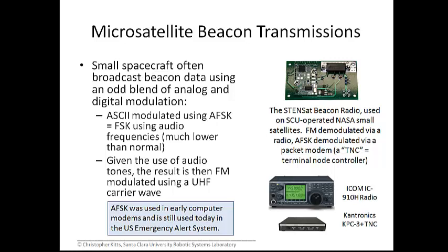So we're not doing direct frequency shift keying of our primary carrier wave. That's not what we're doing. What we're doing is we're frequency shift keying a much lower wave, and then we've created this new wave at a lower frequency, and we use that as the equivalent baseband to do standard FM modulation of the UHF wave. We do this in a two-step process.